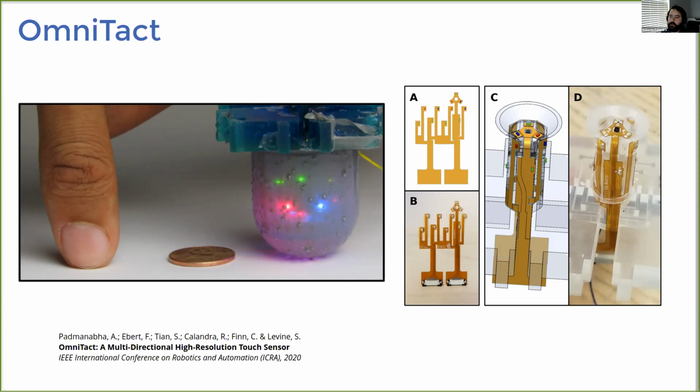In particular, the goal was to develop a sensor more similar to a human thumb in terms of capabilities, such as being omnidirectional and being even more compact. The main novelty that I want you to take home here, which is worth mentioning because it's different from GelSight or DIGIT, is that here we cast the elastomer directly onto the 5 cameras of the sensor.